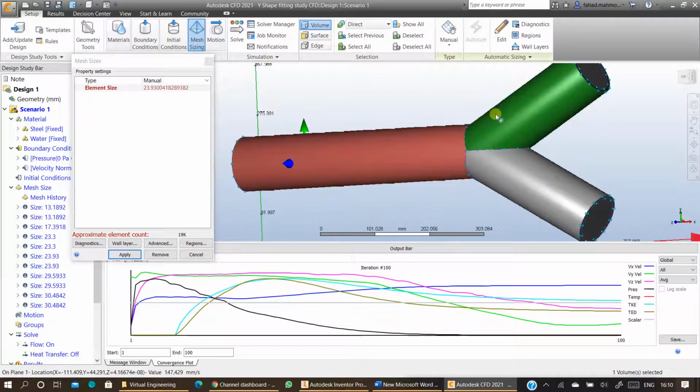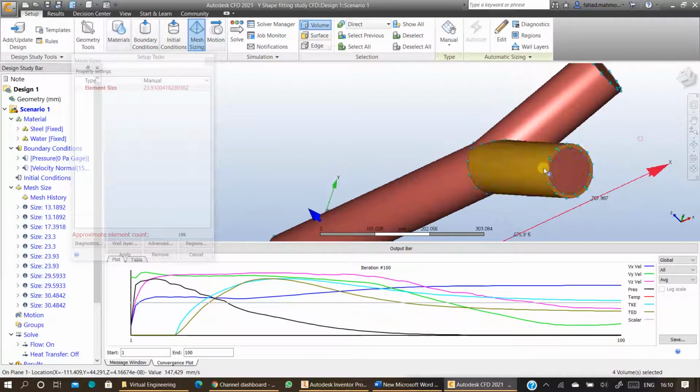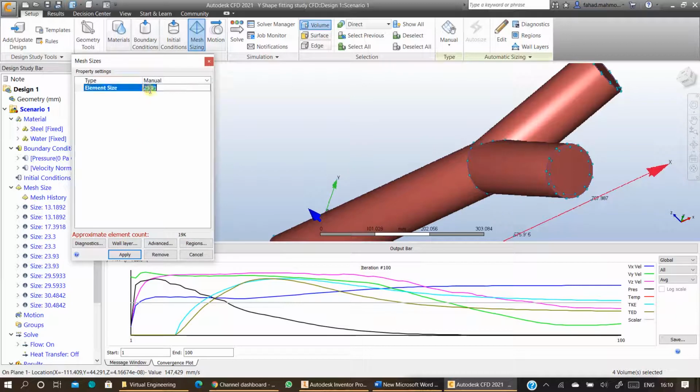and select the entities you want to specify the mesh for. Ensure you select the inner void as well, which you created using CFD, from the front here, and by default the mesh size is 23.93. I can refine it further. You can refine it with increments of 1 and plot a convergence plot like this to show the mesh convergence studies. You can decrease the mesh size by 1 until you get similar results and show the convergence plot. Otherwise, you can just define the mesh directly from here as well.